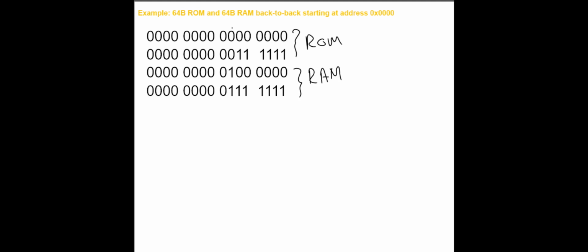For example, if you take a look at these lowest 6 bits, they can have any combination that will continue to be within my 0 to 64, or 0 to 63 locations, right? And any combination of these 6 bits is going to give me a valid address in the RAM.